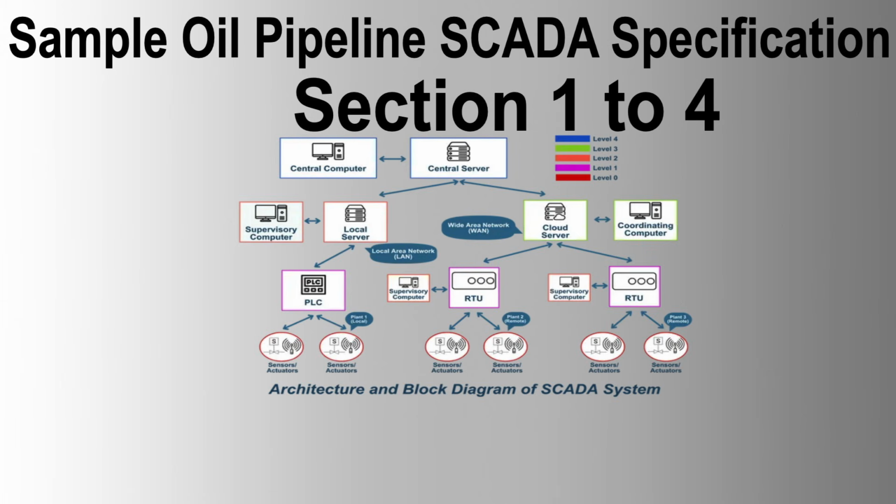Key features: dual redundant Ethernet LAN and open systems architecture. Hierarchical configuration, ensuring local control by LCCs even if MCC and SMCC fail. Communication with Marketing Terminal Tank Farm Management System, TFMS, via dual serial links or Ethernet. 99.9% or better system availability. Expansion capability for future unmanned pump stations and additional monitoring facilities.